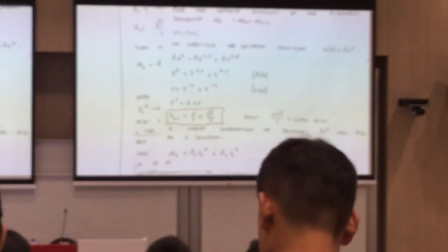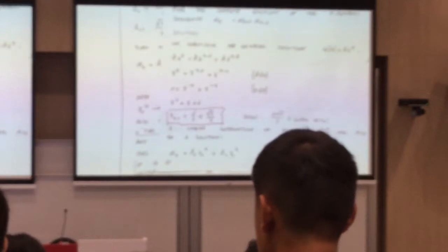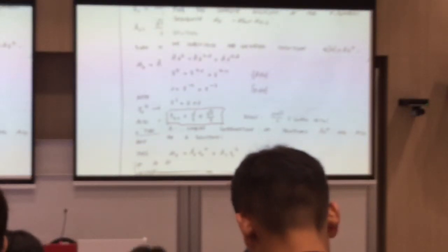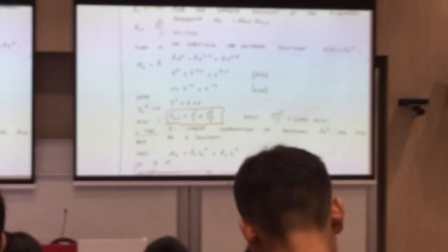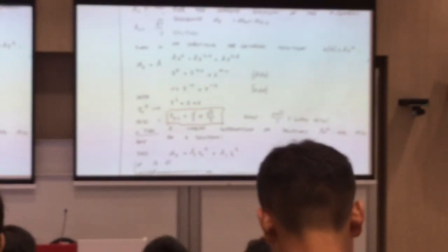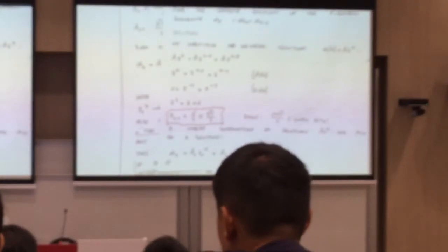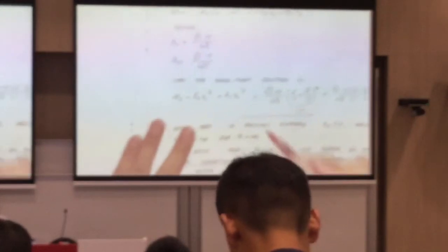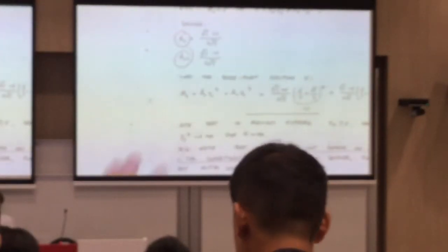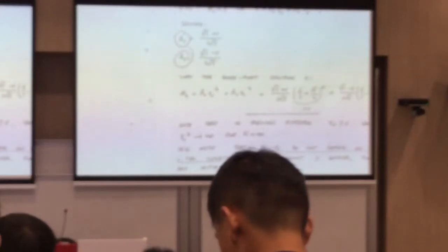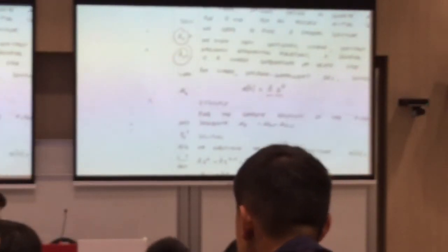And if you notice, and by today you should know, when you talk about stability, it has to do with your initial conditions. You do not necessarily solve the final solution of your difference equation. You only need to solve the characteristic equation, to get your roots Z1, Z2, because the location of these roots will determine the stability. Of course, if you want, you can further solve to get the coefficients. Because for your general solution, you have your roots, and you have your coefficients.